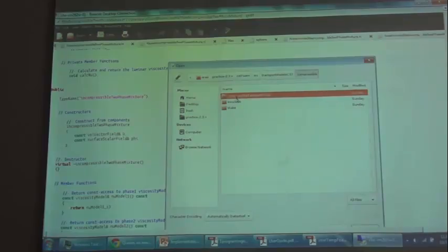The first step is to modify newIncompressibleTwoPhaseMixture.C. I've already opened it here. The main task here is to add the diffusibilities for the two phases. So in the .H file, the new incompressible two-phase .H file, the first task is to go with the declaration of these two variables, and then we have to come to the constructor part of this .H file.